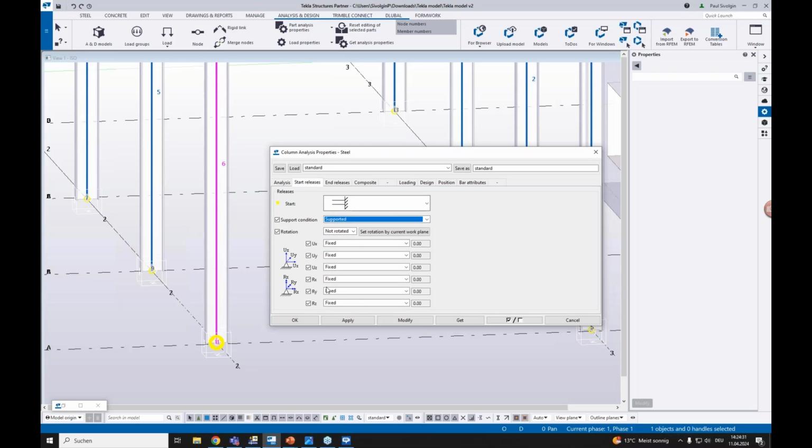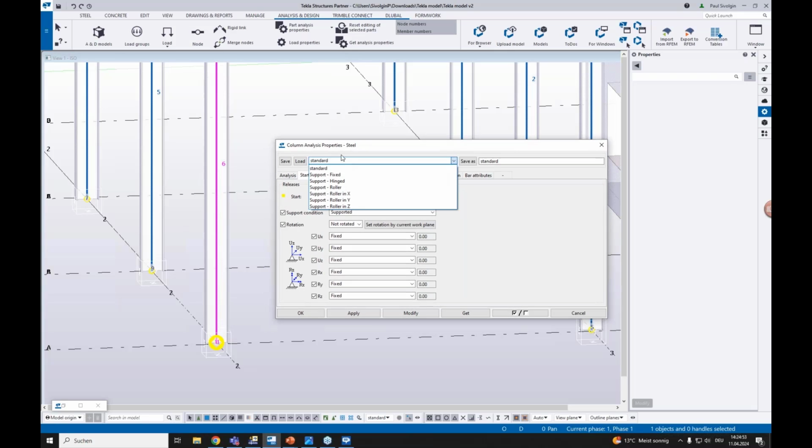So it's maybe some work to always define the hinge you want to use, or often use, in RFEM. That's why it's useful to get some presets like I did. So I defined the typical RFEM supports inside Tekla, so I can just load these properties into my model. So I want a hinge support. You can say, okay, I want to load these properties, and this will load inside here. That's the definition for the hinge support.